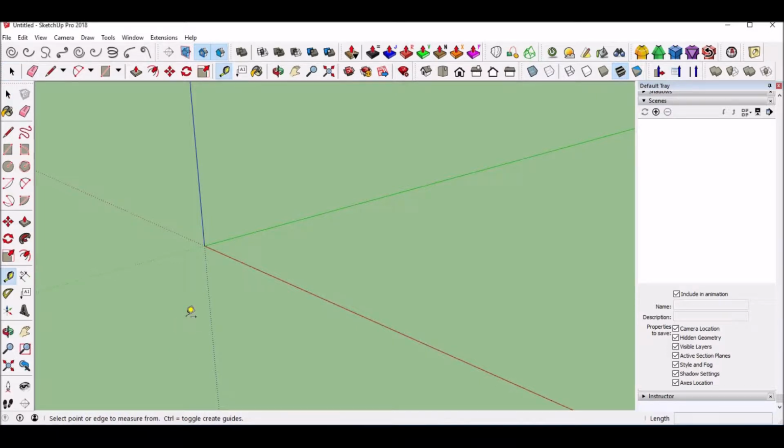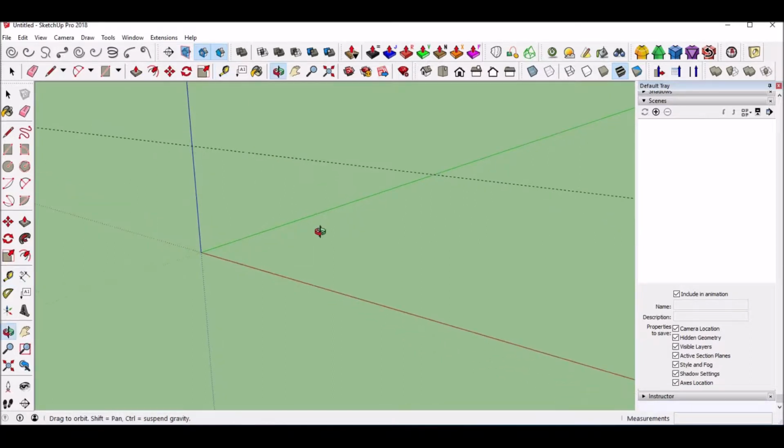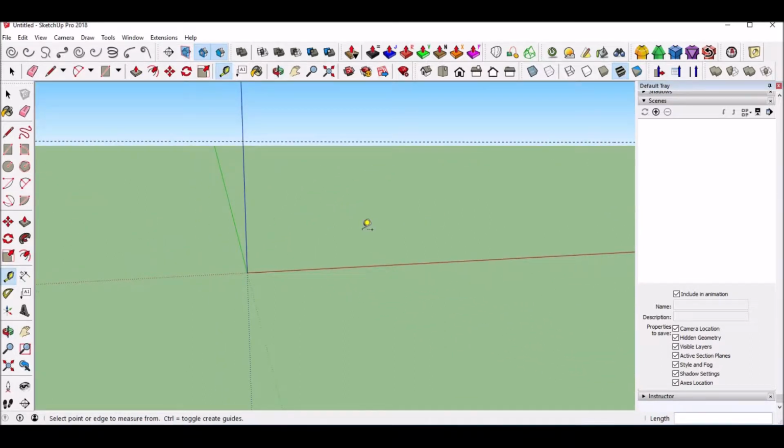So in SketchUp, if you hit T, it'll bring up your tape measure. This is where, if you need a construction guideline, you click on this red axis and drag it. I'm going to hit the up arrow to force it in the up direction, let go of the mouse button, and now type in 25 and hit enter. It's going to put a line 25 units, whatever we are, feet, centimeters, millimeters, meters, above. That way I can get an intersection point right here, draw there.